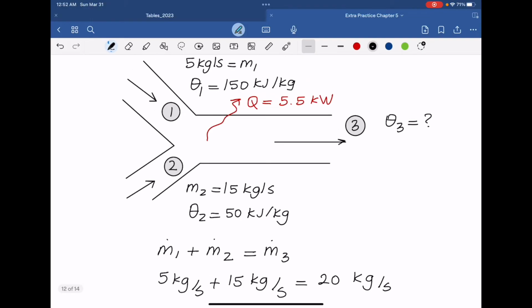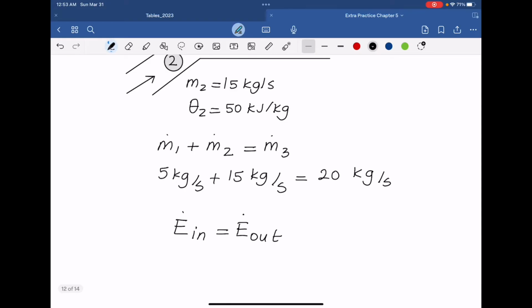When we look at it, we see energy interactions such as energy getting in from number 1, energy getting in from number 2, energy getting out by heat, and energy getting out from number 3 as mass. Therefore, the energy in inlet 1 and inlet 2 is different, because those are two different streams. Therefore, let's now formulate our energy balance.